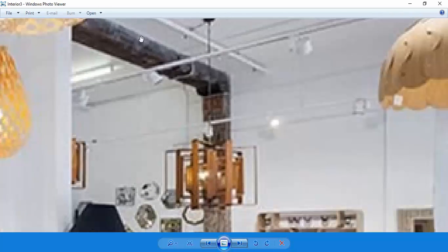So I'd say most likely there is a set of floor joists above this beam that supports the floor above, but then under the floor joists there would be possibly battens framing it out, or maybe the ceiling lining is just fixed directly to the floor joists, but either way you definitely have some sort of ceiling lining there.